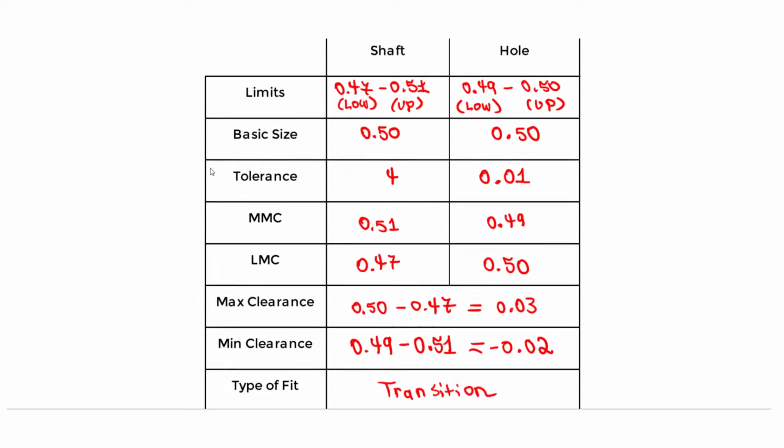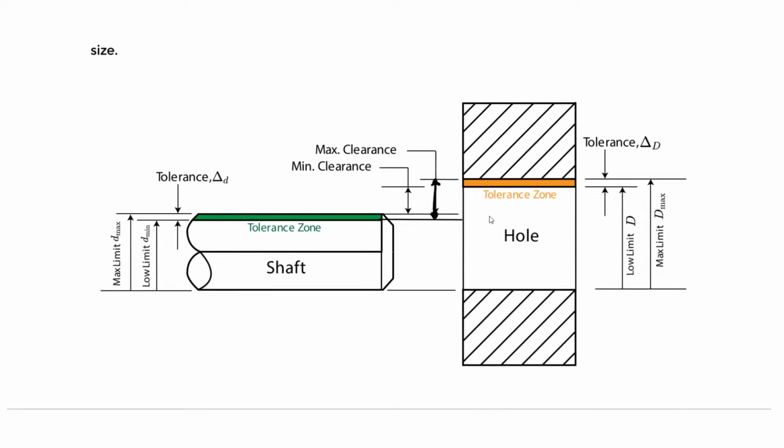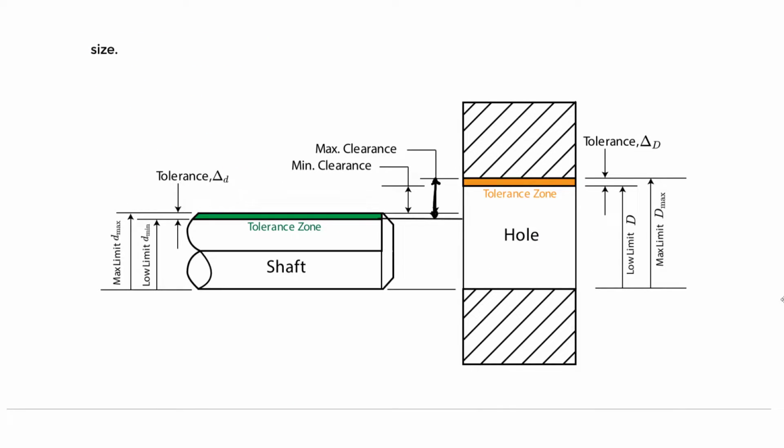So we just simply completed the whole table, and I want to finish off by talking about the deviation stuff in the handbook. They talk about the upper deviation and lower deviation. Let me just mark that on the diagram here. I'll use blue for the upper deviation. For the upper deviation, you always start at the upper side of the shaft, so the very max limit or upper limit of the shaft. Then you go to the lower limit of the hole. So this is the lower limit of the hole, right?